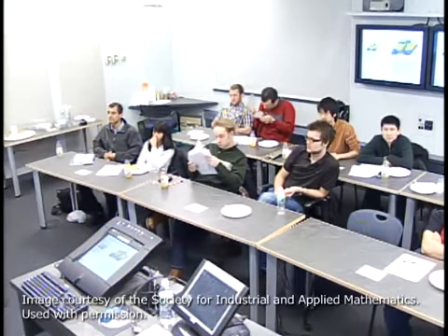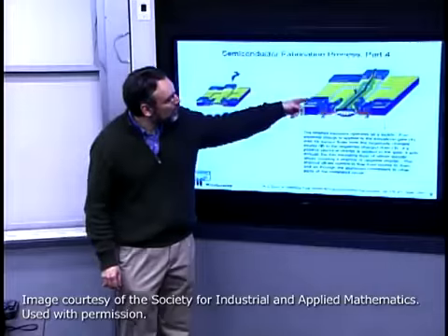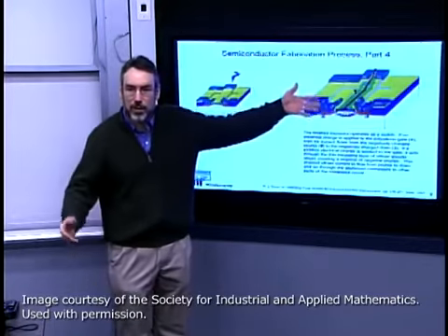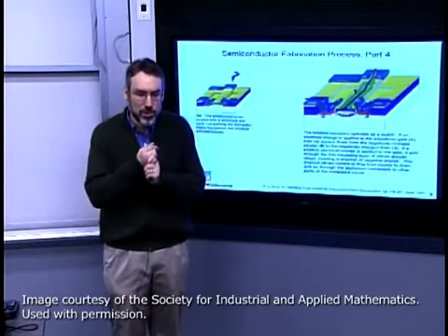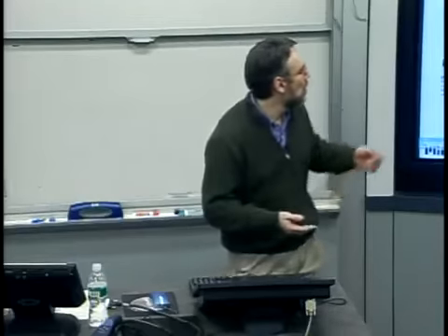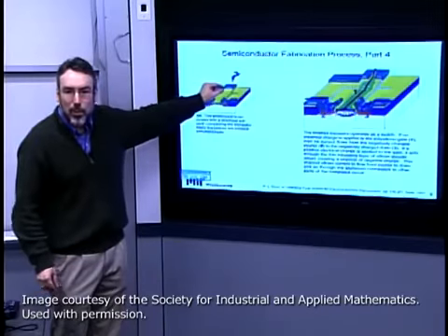Now there's lots of other abstractions in here, and one of the other neat things in this picture is it's showing you're building up a fairly complicated geometry using controllable processes. One of the most important things that you have for control of this lateral differentiation is photolithography. Notice we were never just depositing directly aluminum where we wanted it.